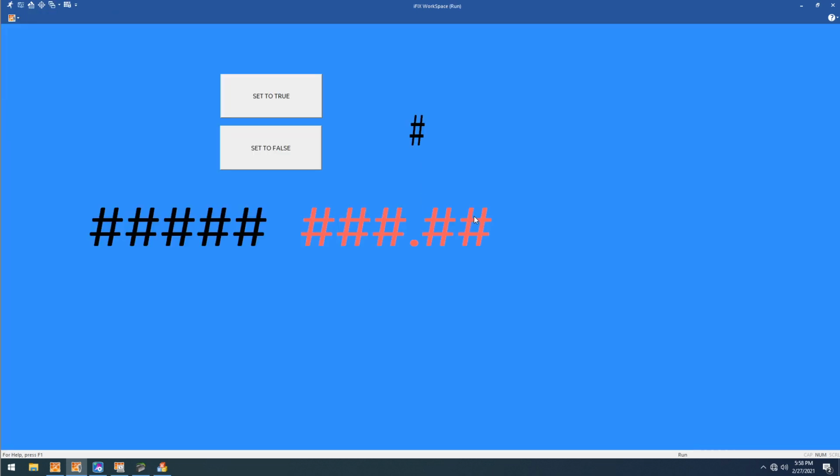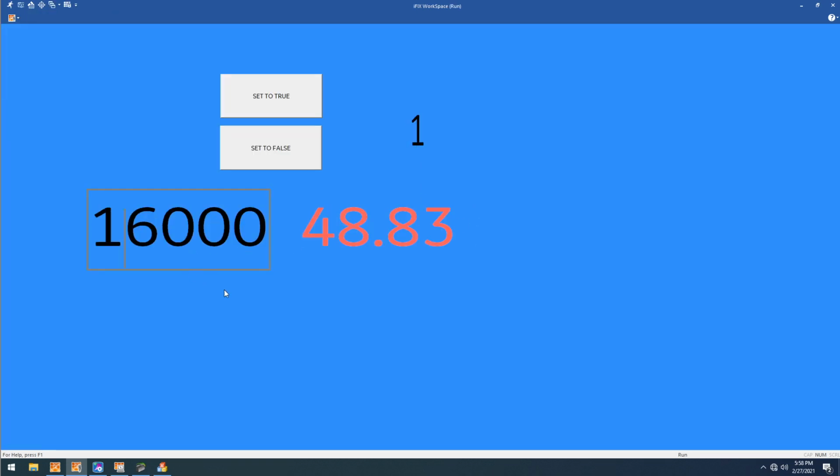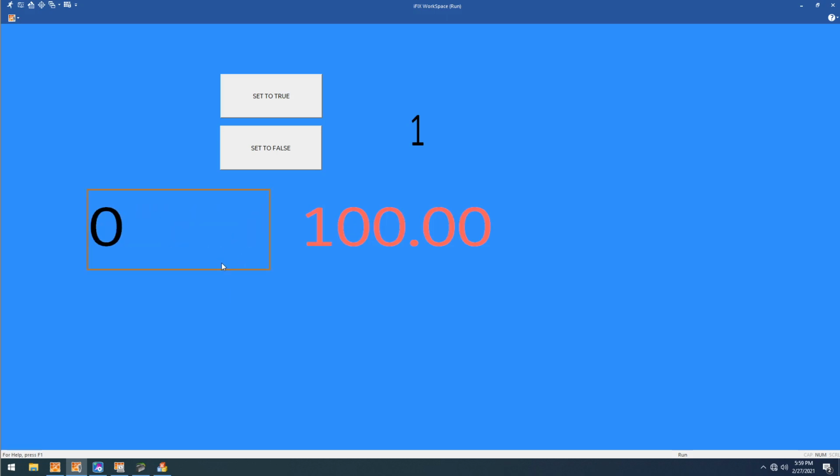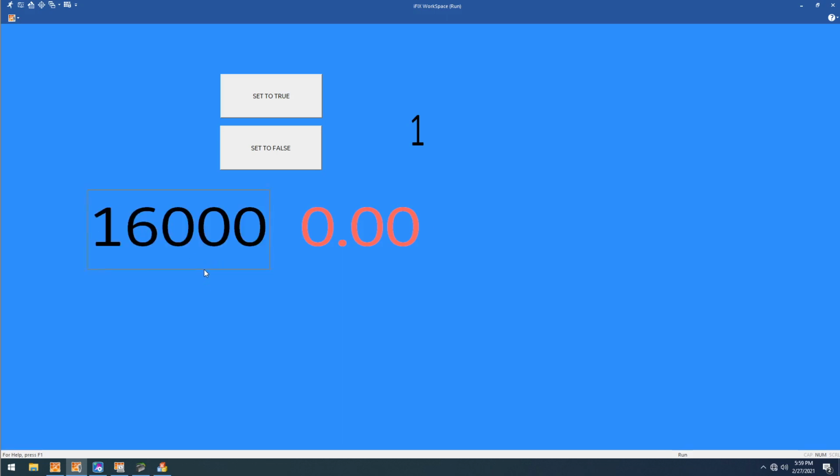So let's go online. So what is 32,767? That should be 100%. That's our max. Cool. How about 0? 0 should be 0. Okay. How about, say, 16,000? That's roughly 50%. Okay, 48.83. Fair enough. How about 18,000? Cool, 54.93%. So as you can see, iFIX can be used to condition raw signal values into something more meaningful, or